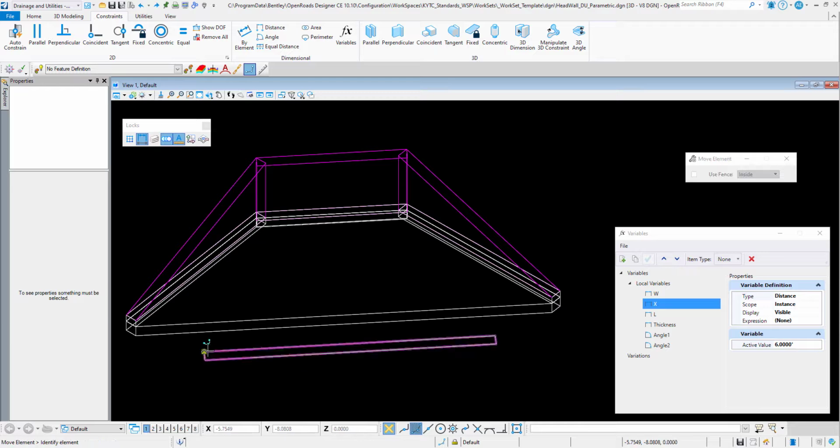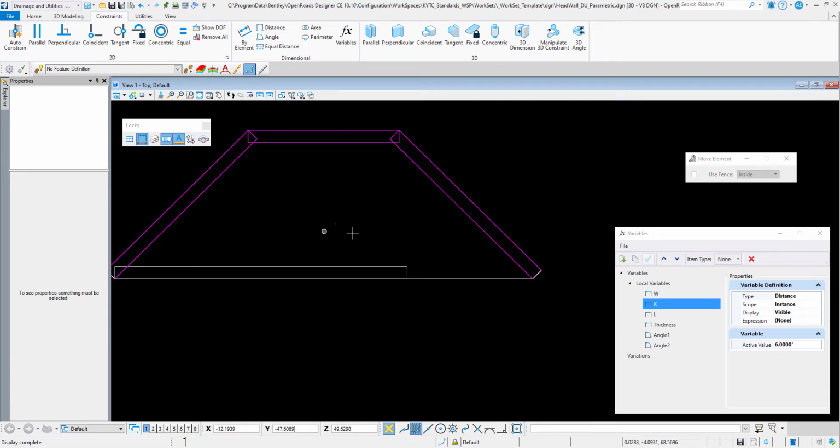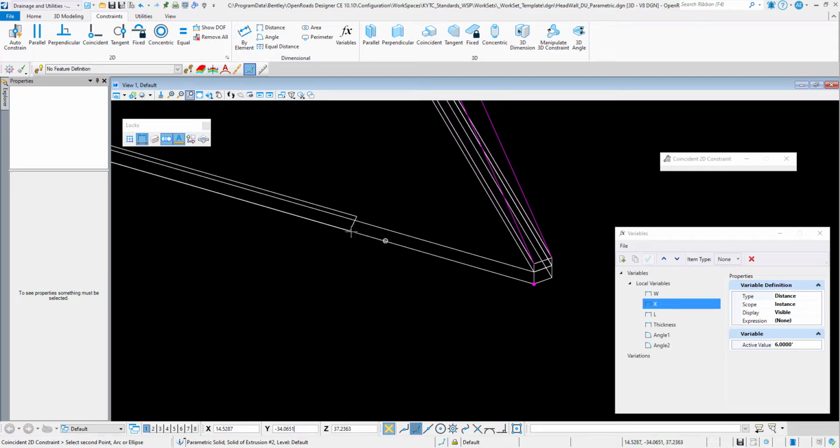Now I drew it out in space this time. I didn't trace over anything, but you can easily just move them in three-dimensional space. Just make sure I grab one of the edges and move them to the correct plane. A lot of people may employ AccuDraw to make sure that they lock in some of their planes. And all I'm doing over here is just constraining these edges.